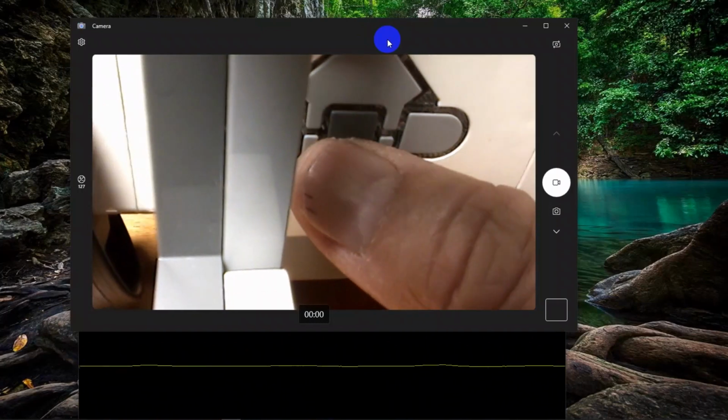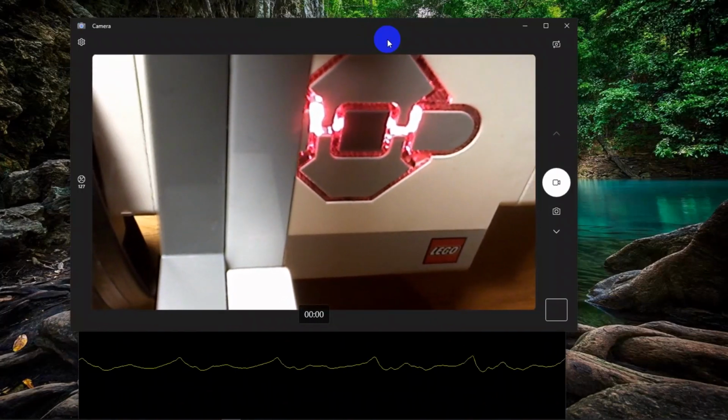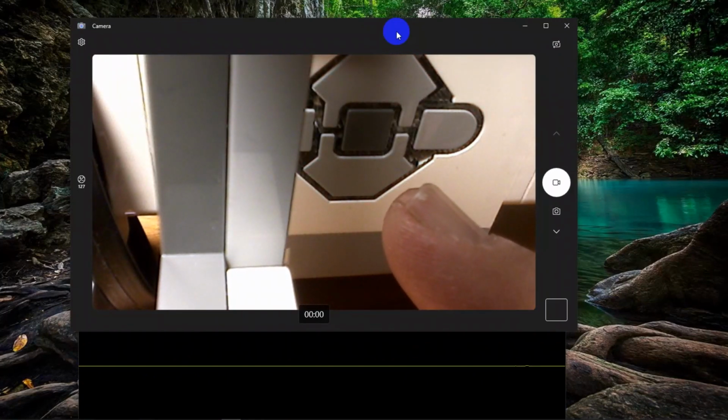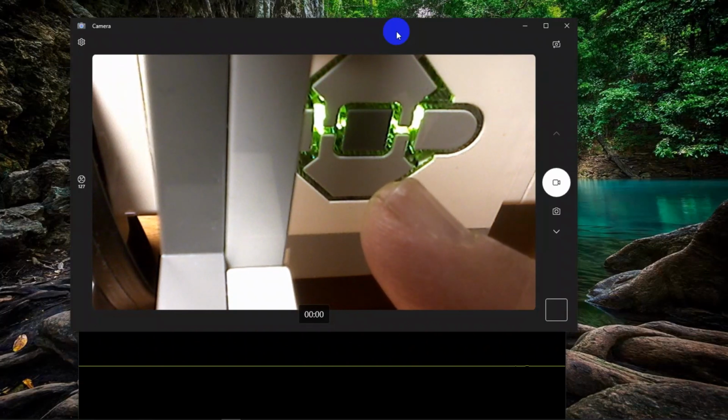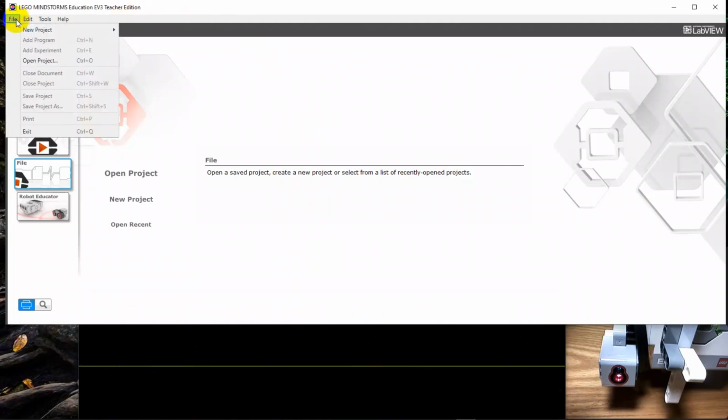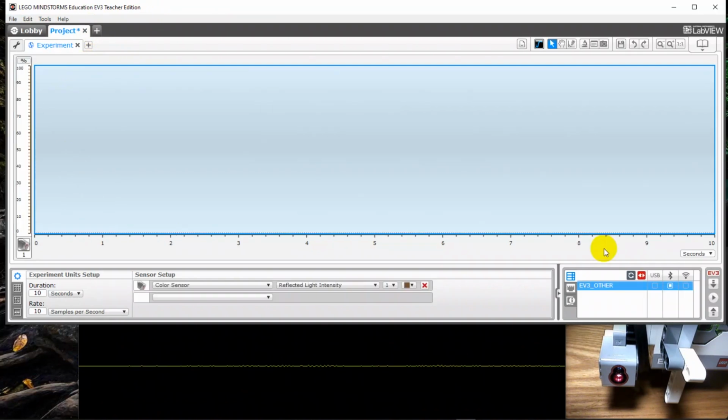First thing is powering up the hub and waiting for a few moments for it to come to life. From the main menu of the app at the top we access the File menu. Then we choose New Project and finally we choose to do an experiment. We should connect the activated EV3 Hub via Bluetooth, by ticking the empty square next to its name in the list. If the hub is not there, we check if Bluetooth is actually active on the hub.